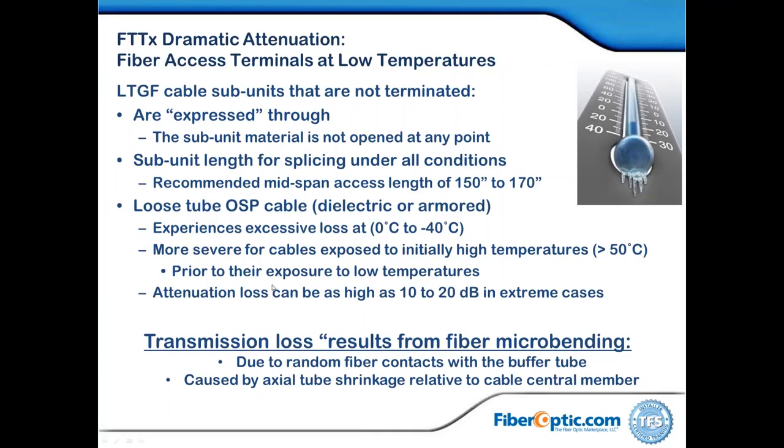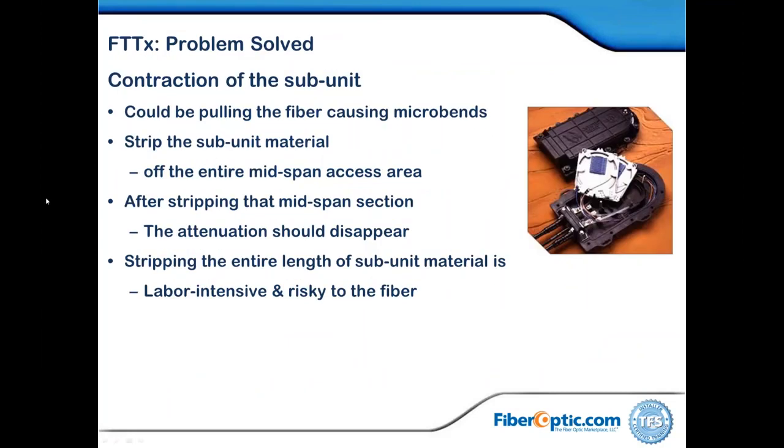There are things for sub-zero. Don't want to go too long, say certainly past an hour on this. But again, if you want to go back in, if you're in real cold environments, there are some things you might have to do resulting from transmission loss or microbends, how things are curved or how you put them in the splice tray. And that's about contraction of subunits, how you can adapt for extremely cold as far as expansion of the plastic buffer gel-filled tubes. You notice here you can strip all the buffer tube out of the splice closure, and then the individual fibers are free.